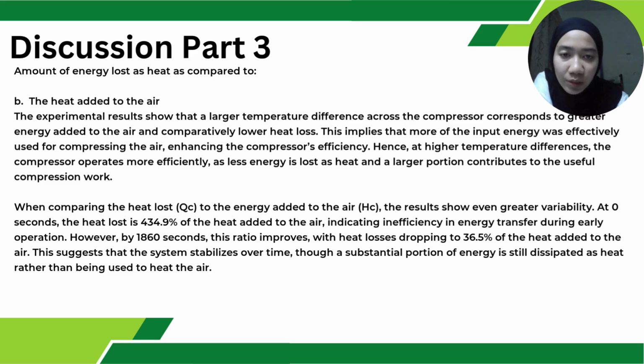The experimental results show that a larger temperature difference across the compressor corresponds to greater energy added to the air and comparatively lower heat loss. This implies that more of the input energy was effectively used for compressing the air, enhancing the compressor's efficiency. Hence, at higher temperature difference, the compressor operates more efficiently, as less energy is lost as heat and a larger portion contributes to the useful compression work.